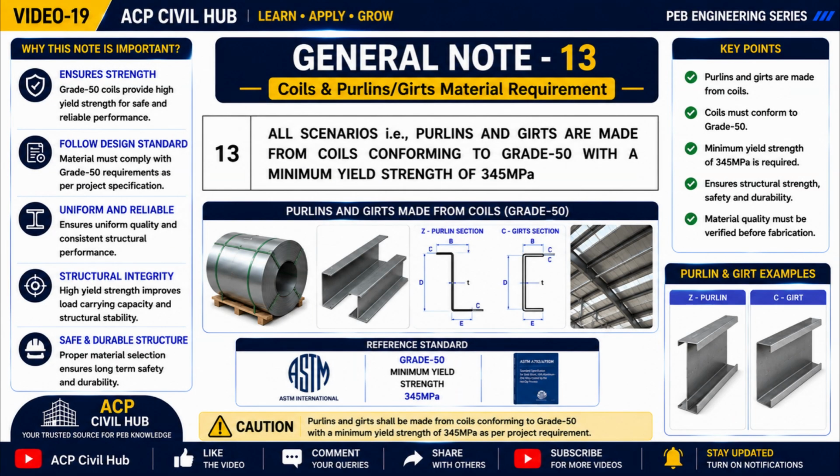Now let's understand General Note number 13, which specifies the material requirement for purlins and girts used in a pre-engineered building. According to this note, all purlins and girts shall be manufactured from steel coils conforming to grade 50 material. The specified minimum yield strength is 345 megapascals, providing higher strength than ordinary structural steel while keeping the sections lightweight and economical.